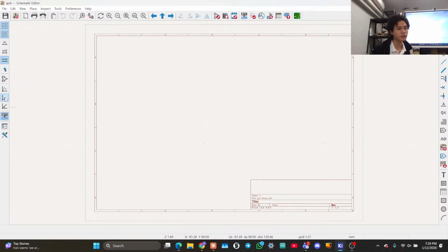You see this tree here, set line mode to the middle one: horizontal and vertical lines only. This is purely for readability. I'll show you later, but for now just set it to this and take my word for it. Annotate automatically should be yes. Hierarchy, navigator, and properties we don't care about. You care about this, which should be set to this one. Click this, not this, this. Then set to mm for everyone's convenience. On top, most of it is rubbish, we don't care.